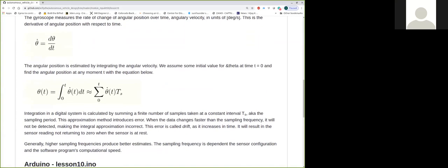All right. Now, the summation time, or the sampling time, influences how well we capture the data. The more often we can sample the data, the faster we pull in this information, then our assumption that that rate or that change has been constant over that interval is more likely to be true. So the faster we sample, the better results we get.